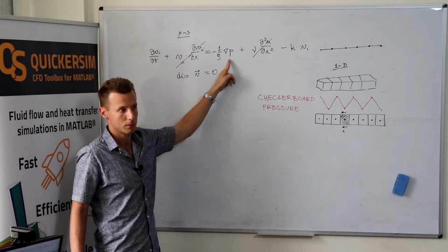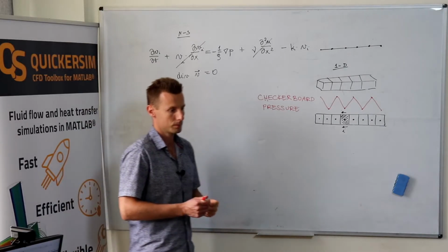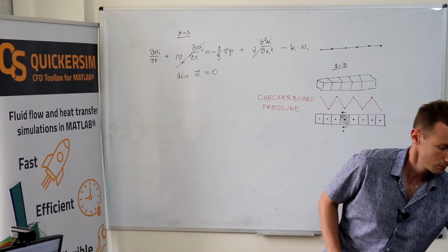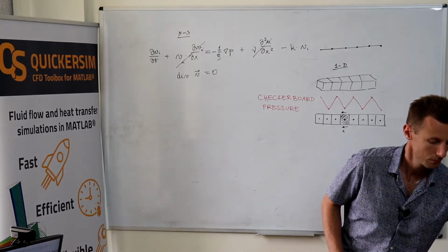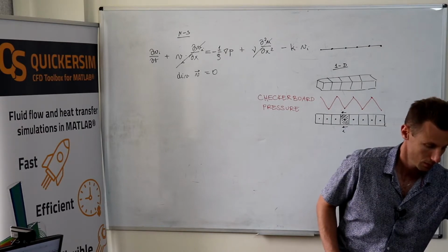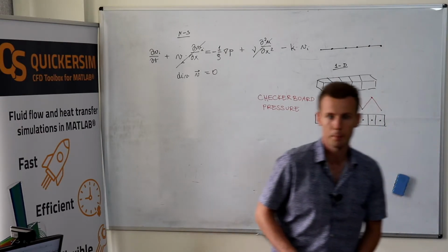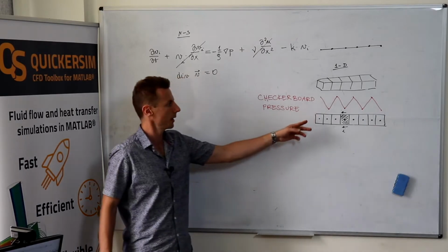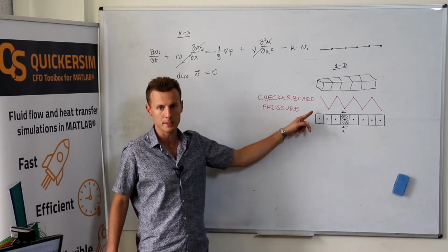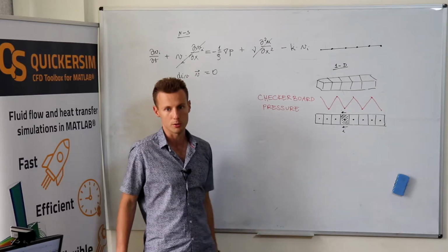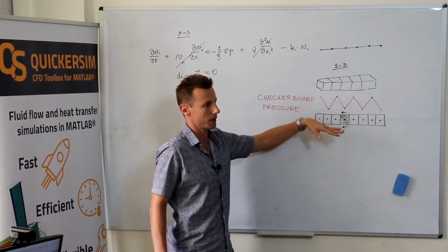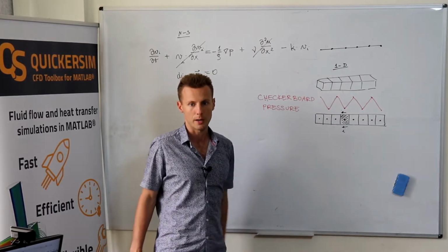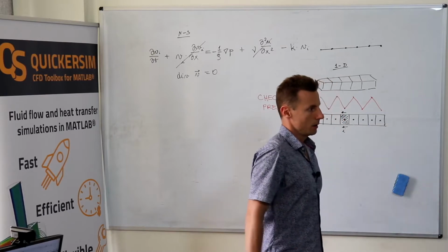Yeah, like if you had the velocity inlet and pressure outlet, you would have constant pressure on half of the cells. At least it's constant on half of them, but it's still unbounded on the rest of the cells, I think. Yes, exactly. Like you can quickly generate numerical instability in your solution procedure. If any perturbation arises, then it can quickly grow without any limitations.